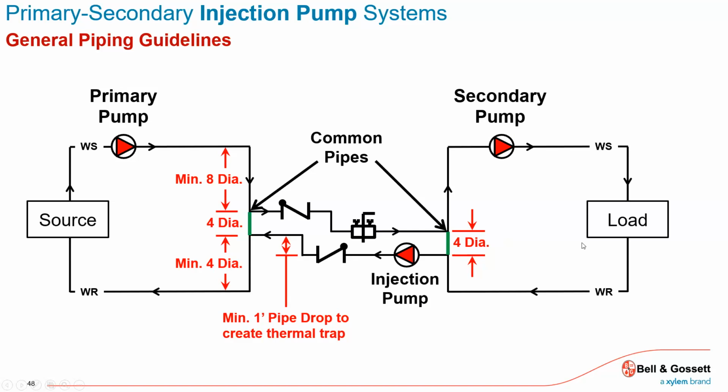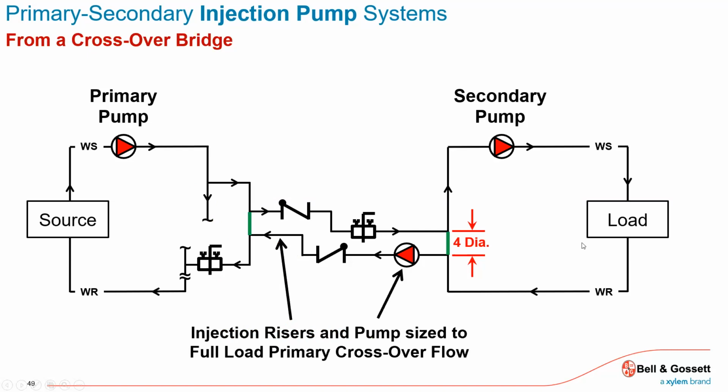And again, you start getting into some of these applications. This is very common. We get involved with this a lot, injection pumping, where I have a heat source and I have a load over here. And instead of maybe using a valve, I might use an injection pump. That pump is going to take some of this hot water and inject it in an equal amount of return water back. Whatever doesn't get injected back moves across that common. I've got some blending, some mixing right there. So I can do all kinds of things. We do it all the time.